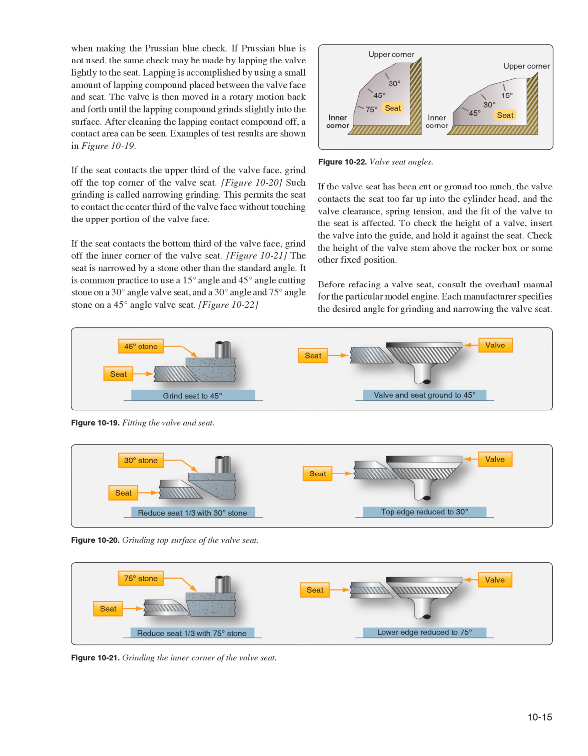It is common practice to use a 15 degrees angle and 45 degrees angle cutting stone on a 30 degrees angle valve seat, and a 30 degrees angle and 75 degrees angle stone on a 45 degrees angle valve seat.